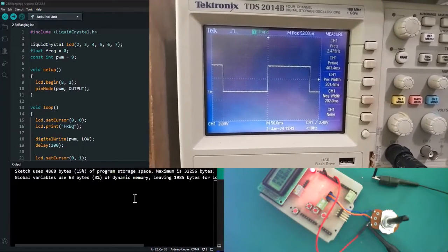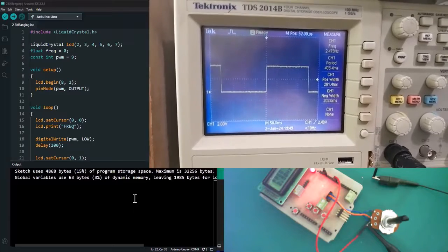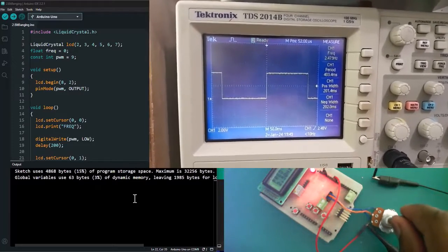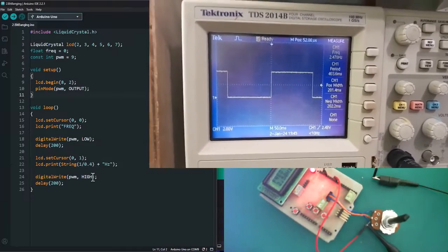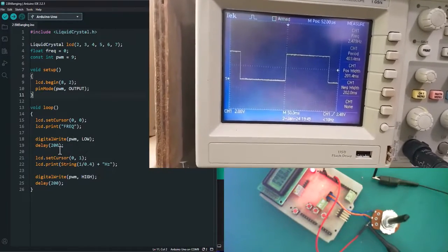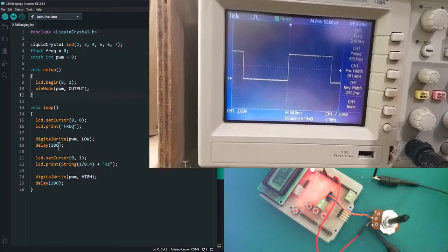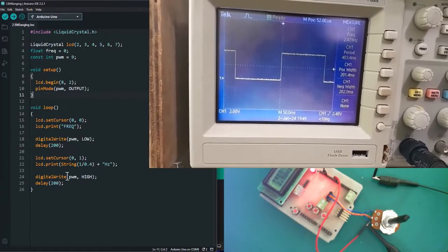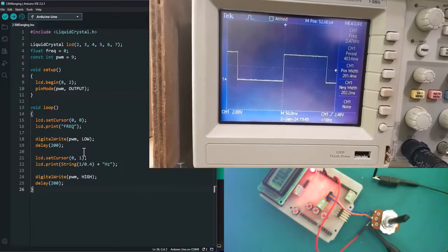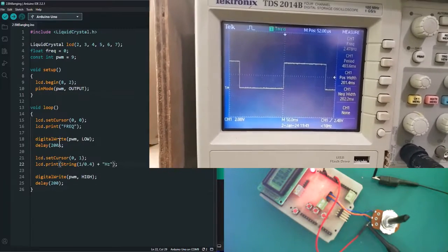So it gives us a period of 400 milliseconds. Now remember, this one you cannot change the duty cycle because it's a bit banging PWM signal. Or if you want to change the duty cycle here, you need to shorten the time in which you are turning the pin on and off. Let's go ahead and try to achieve that.